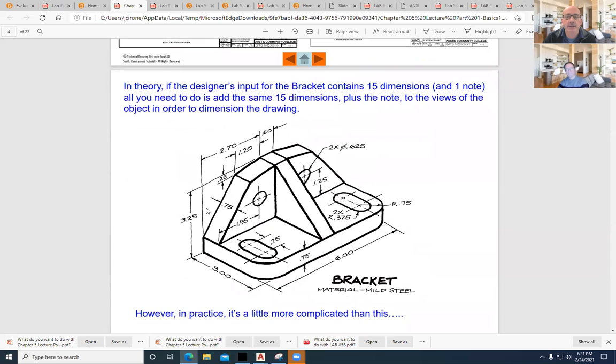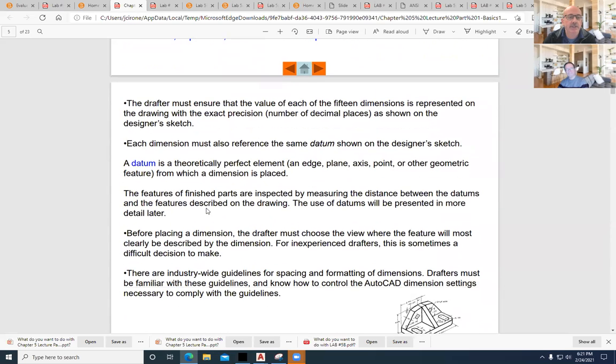They talk about the necessity of making dimensions, and what it is that you need to do. When I was a design engineer for Signode, a lot of times you would just over dimension things. You would put on everything they needed to dimension it. If you don't, you'll get called down to the shop floor because the guys can't make it, and it's not their fault if the dimension isn't on there. You want those guys to help you, so you want to be really cooperative when you work with the shop guys. They're there to work together with you.